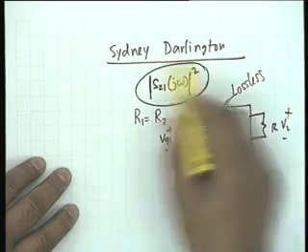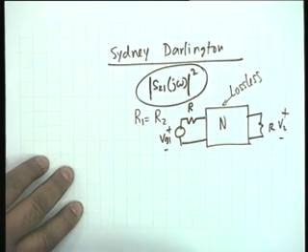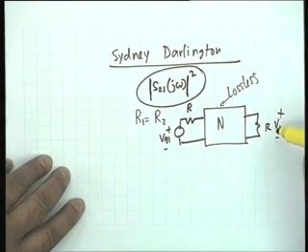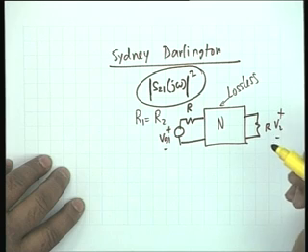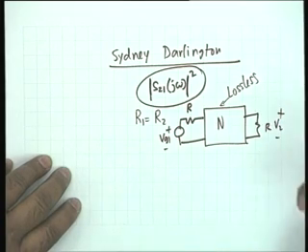Suppose this is specified, S21 j omega squared. Now, usually this is not what will be specified. What will be specified will be the voltage ratio V2 by Vg1, the transfer function. But if you know what is V2 by Vg1, then you also know S21, isn't that right? Because S21 is simply twice V2 by Vg1.